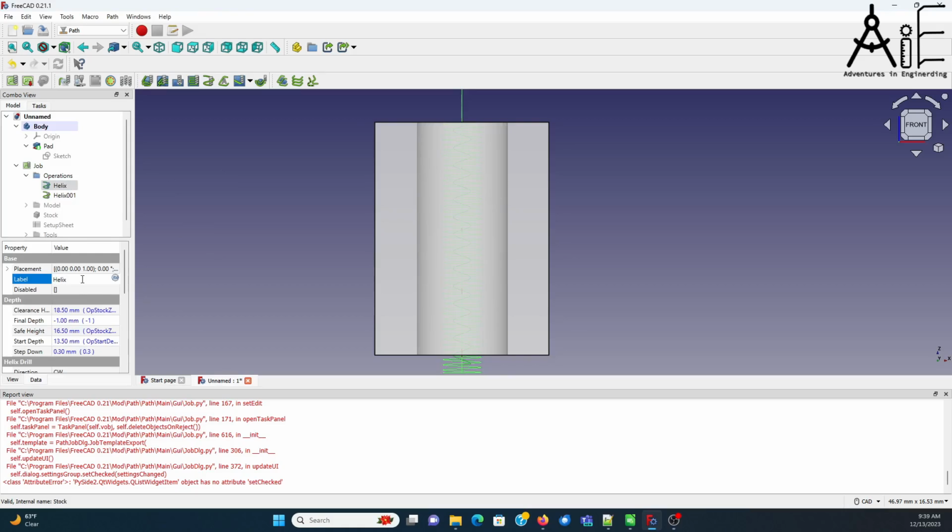This is a helix tap hole. It's going to be the helix thread 1, the first thread hole. Okay, and then we're going to add another thread hole, which is going to be essentially the same thing, but with a larger diameter to get to the final thread pitch diameter.